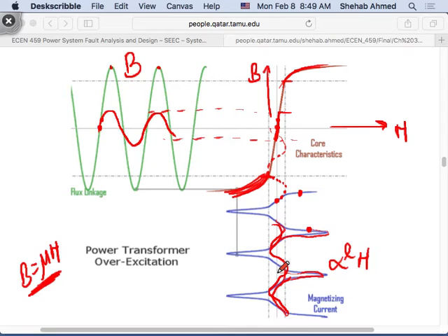Sometimes harmonic content in a power system is not acceptable. It may correspond to the resonant frequency of your generator, and hence you're supplying a certain value of voltage or current at the resonant frequency of an electrical circuit. What will happen? It will be amplified. So you will get very large torque ripples at that frequency, for example. That's one thing that's going to happen here.